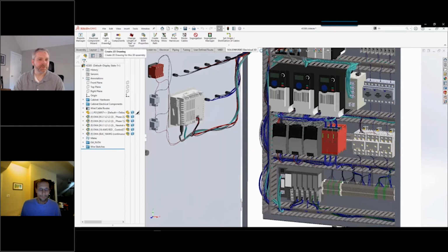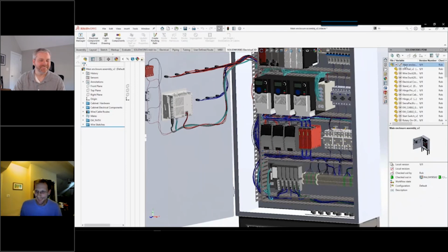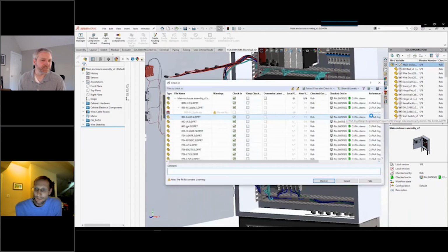And so now you have a 3D cabinet assembly, and the system knew which parts to put in and how to follow the wiring paths automatically? Automatic, right? Like I say, Joe, it's all automatic. Yes. As long as your schematic is right, it is automatic. Your schematic is right and your library is properly set up, exactly? Correct. Yeah. So the wires know to look for ducts, and they know where to land on each component. That is the truth too.